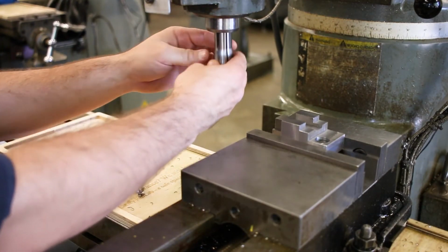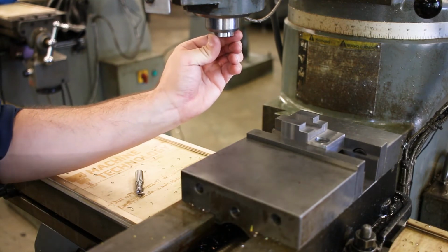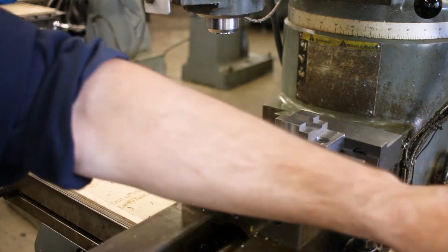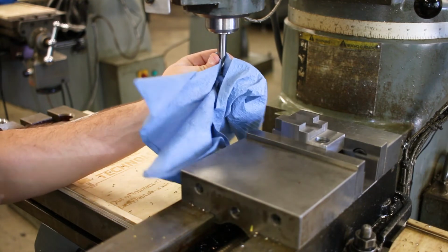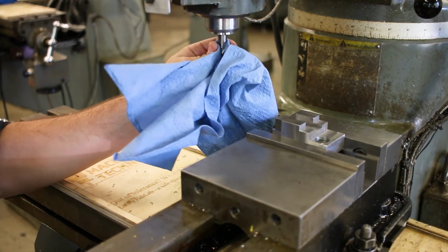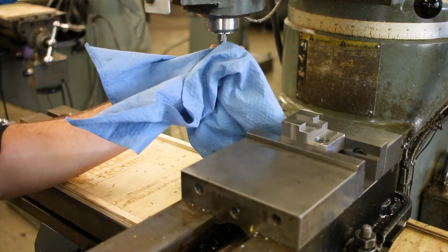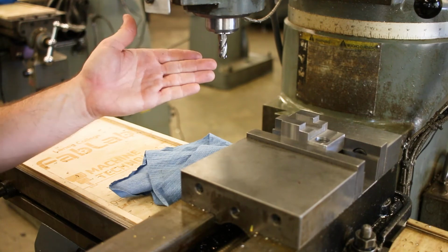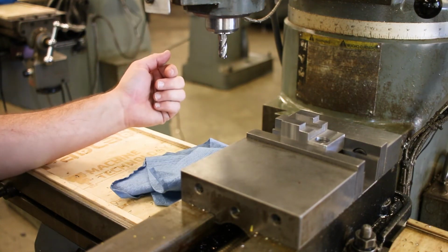All right, the 1/2-inch collet goes in. Get that started. A little bit closer than that. Okay, and now our carbide end mill. It is pretty sharp, folks. So it's a good idea to wrap a towel around it. Okay, get that started. Now, really, please, one way that you can keep these things safe is to put something soft underneath them, right?